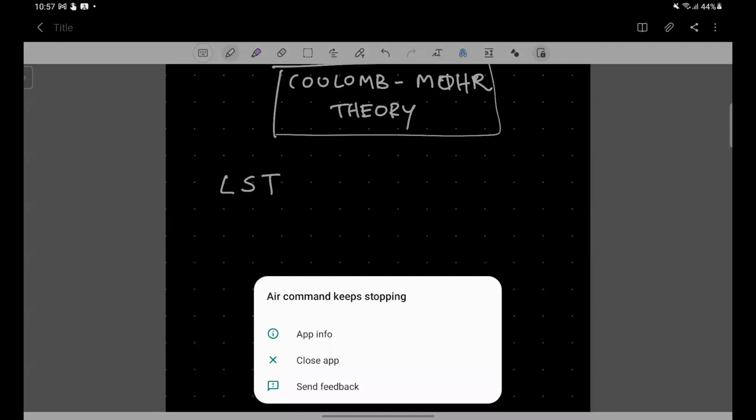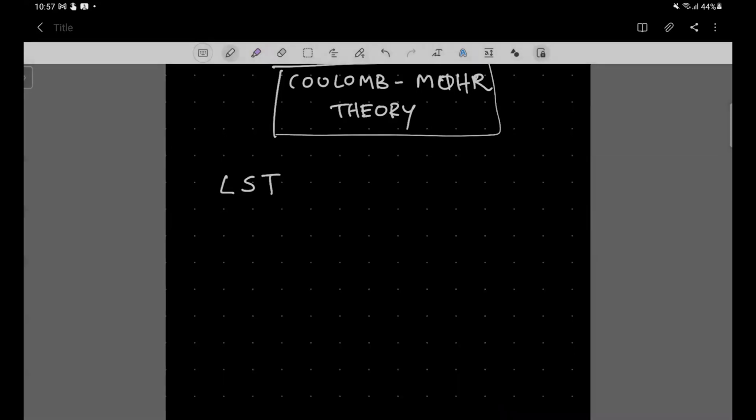As you can obviously think, this linear variation also comes with an additional computational cost, meaning we will have to introduce more degrees of freedom. More degrees of freedom means we need to use more sophisticated shape functions to capture this linear variation of the strain.